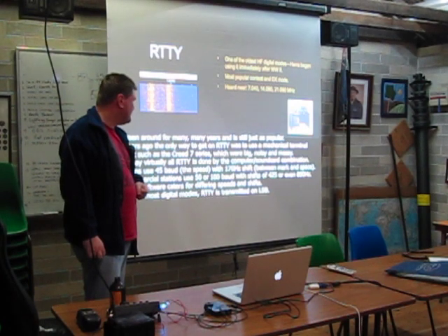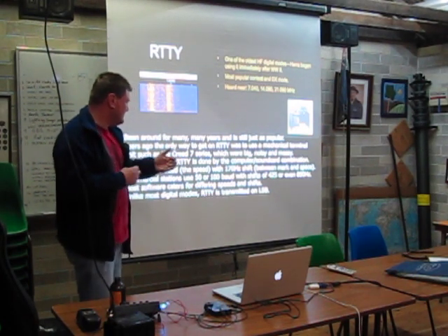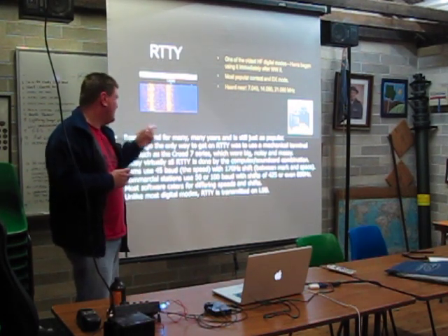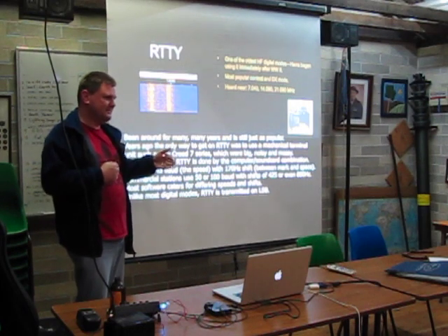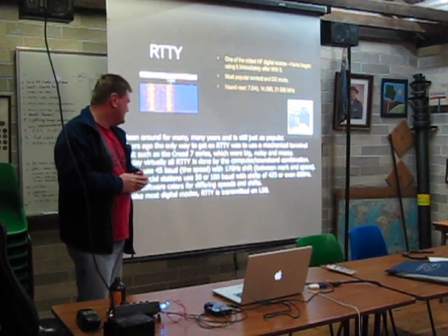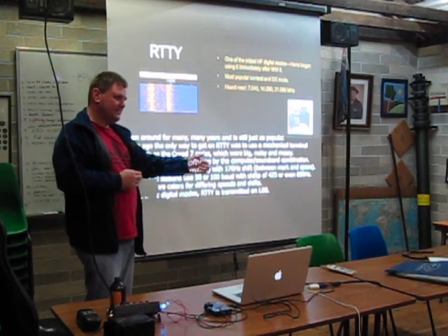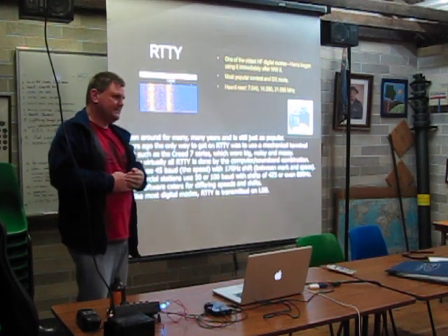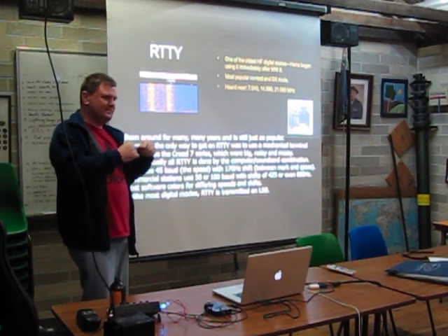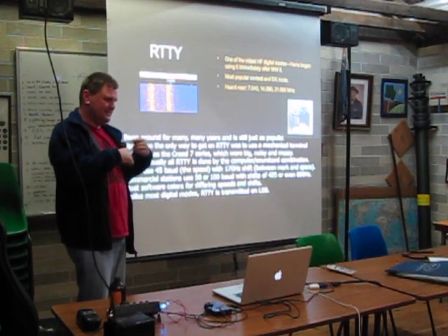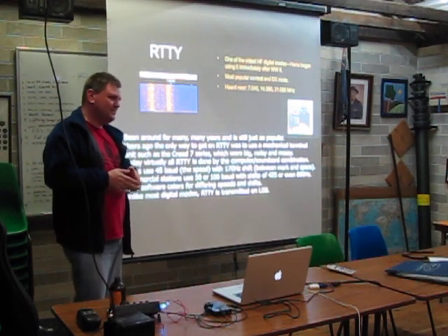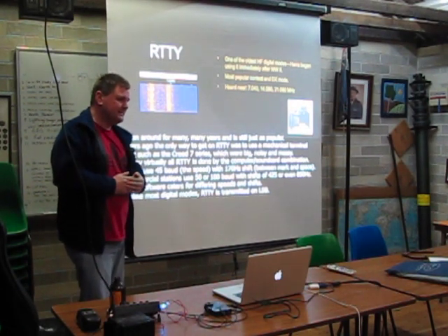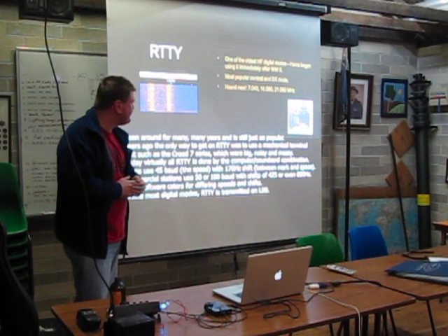Yeah. So the check bits are quite good because they can detect when there's a mistake in the transmission. If you decode the tone incorrectly, then the check bit won't match, and so you know that there's a fault. So that's what's known as forward error detection. And some of the modes are even so sophisticated that they can work out which bit was incorrectly received, and fix it. So if it can fix it, that's now called forward error correction, which is really good. So we'll talk about that in some of the upcoming modes.